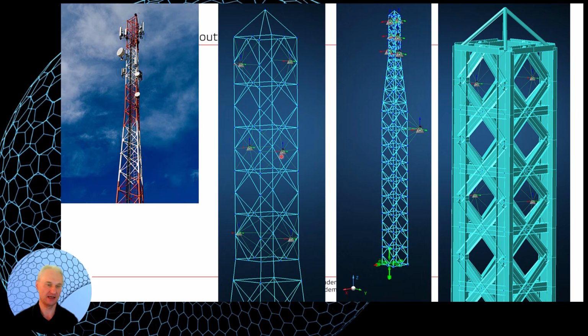So here the antennas are attached, or represent, I should say, not the stiffness of the antenna, because the stiffness of the antenna has no influence. What is important is the stiffness of the tower, but the mass of the antenna is very important. And also the boundary conditions. So typically here we know that the tower is firmly grounded on the ground. So the tower is restrained at the base in the translation and rotational degrees of freedom.